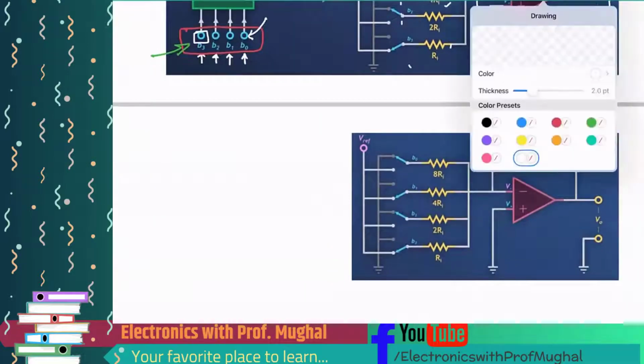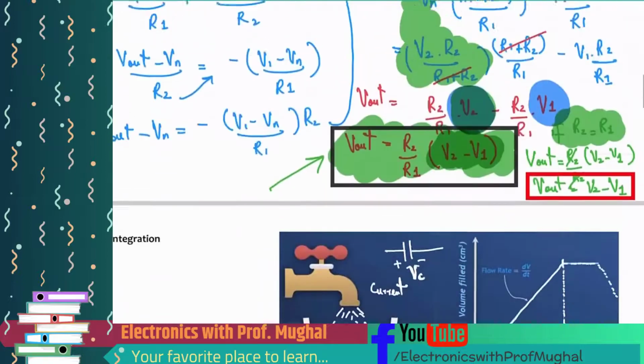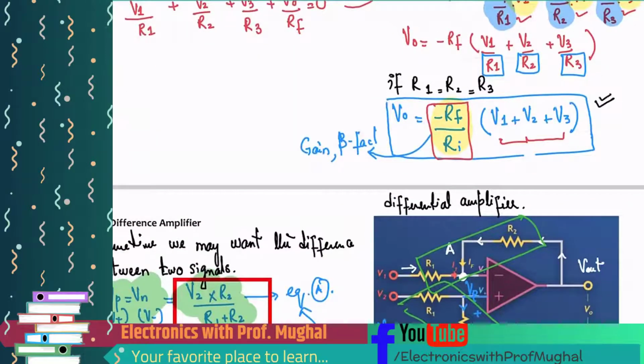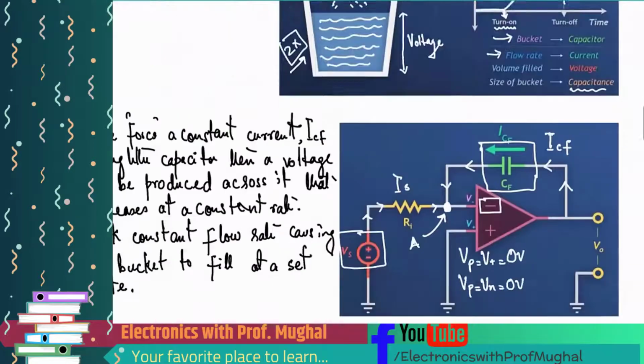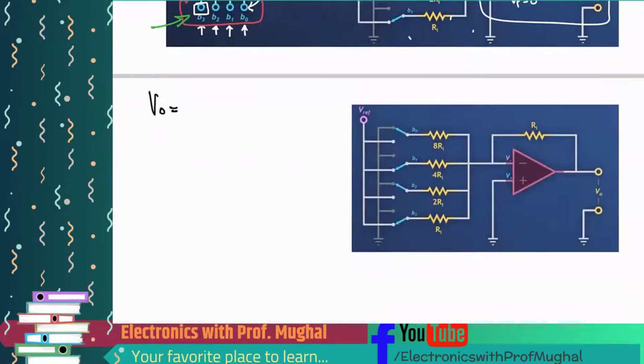So what was the output equation of the summing amplifier we just derived? Anybody remember? That was the first example, right? What was the output equation? Minus RF over RI, and in brackets V1 plus V2 plus V3 and so on, V4, however many we have. So I'm going to apply that same thing over here.